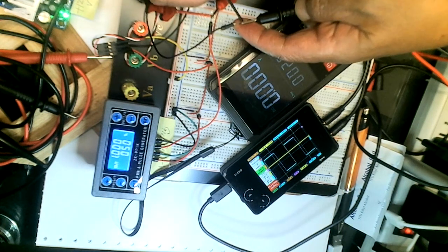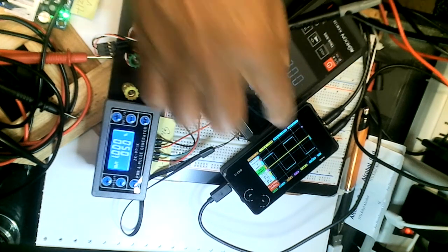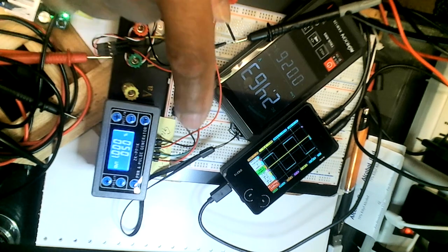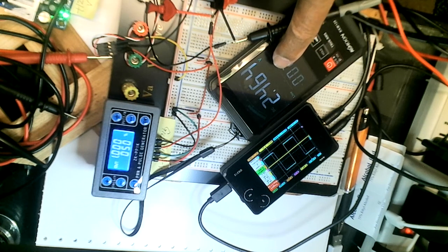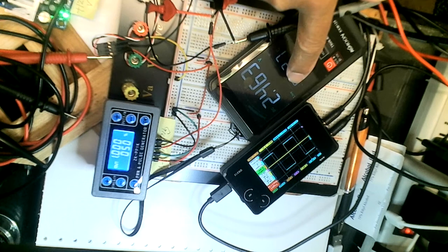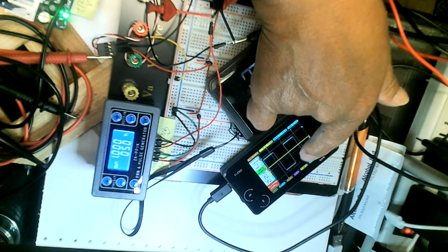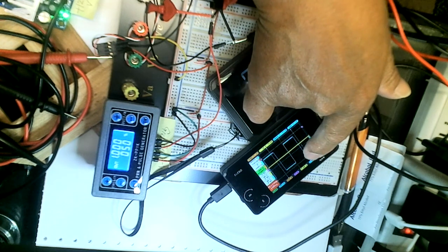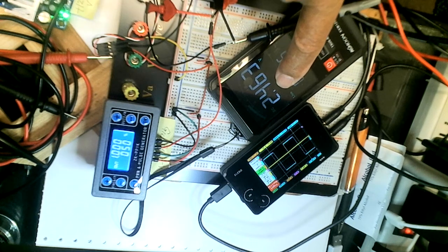Now, a very simple setup. We measure the output voltage. It's a 5 volt signal. The average shows 2.463, right? It's slightly less than 2.5 because this is not exactly 5 volt. It's the TTL output, slightly less than 5. So the average becomes about half of that.